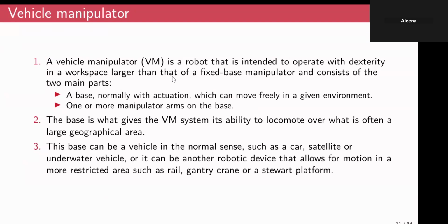One example is that if we fully stretch our arm, that extreme point where we can reach with our finger, we can only reach by a single orientation. But any other point that is close to our body, we can reach with any arbitrary orientation. So dexterity basically means you can reach a point with all sorts of orientations, and a vehicle manipulator essentially imparts an unconstrained dexterous workspace.